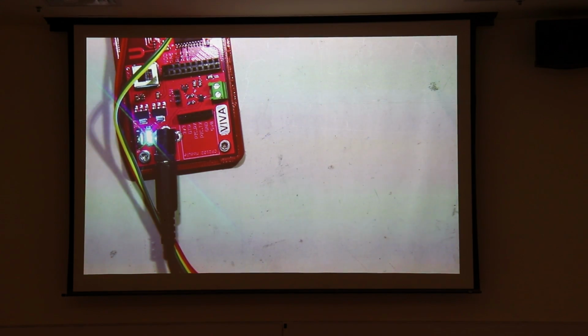When we turn this transistor on, it's going to pull this line low. When we turn the transistor off, this point's going to float. So we just put a resistor here, maybe 3.9 K, but you can use values between 2 and 5. And we're going to pull it up to VCC.